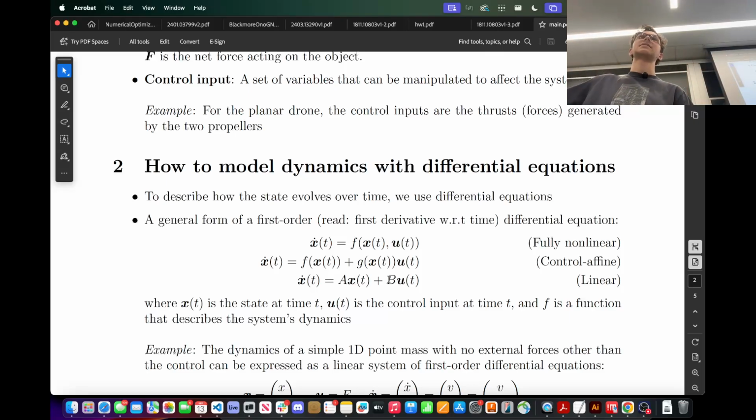Does it oscillate? Does it decay? For example, if you have a mass spring damper, a mass on a spring with velocity damping, that's going to go back and forth with oscillations, but then eventually over time it's going to decay to 0, right? And so with no control input, you would expect that system to decay to 0.